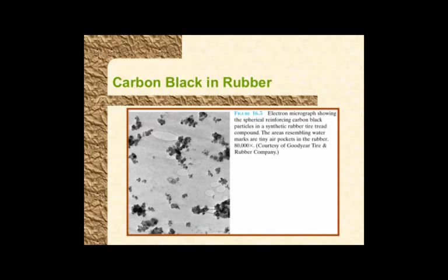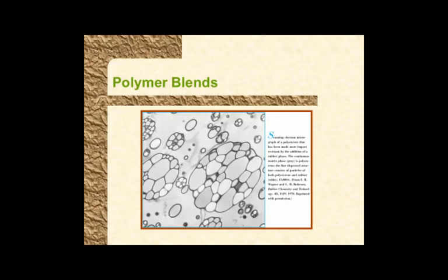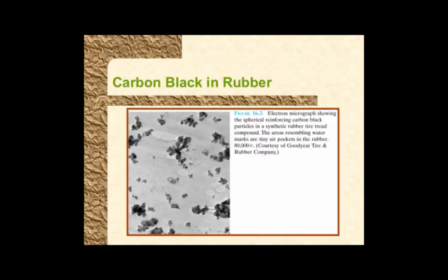So it comes back: if you didn't have the right carbon, the right dispersion, or the right curing temperature, you're going to make a defective tire, right? And that can result in loss of life. From time to time you hear of 5 million tires recalled or something like that, and you can imagine what the loss is, and what the penalty is in case they are not recalled, right? So mixing matters. That was in the case of particles of carbon in a polymer.